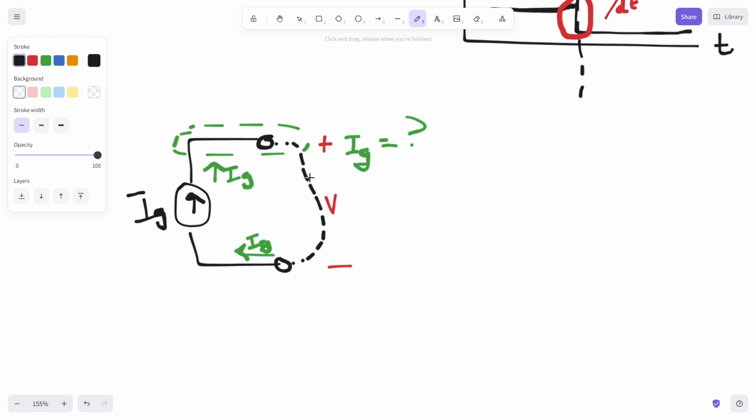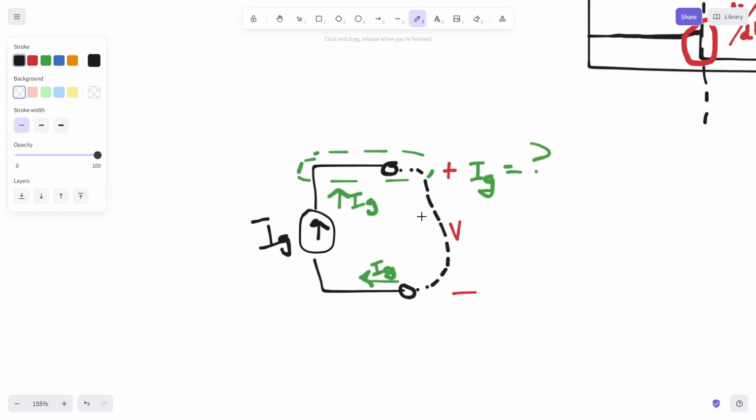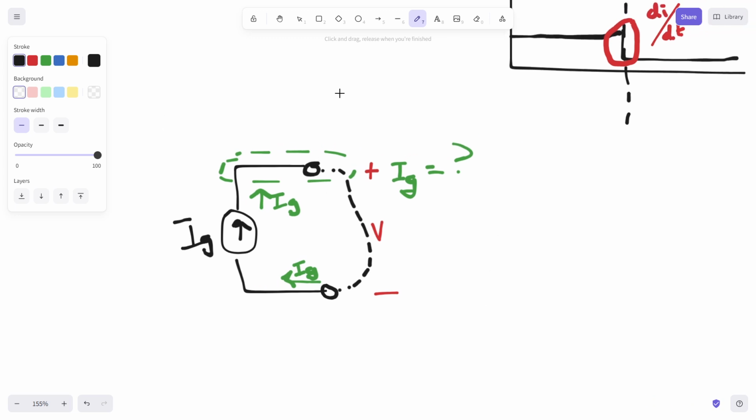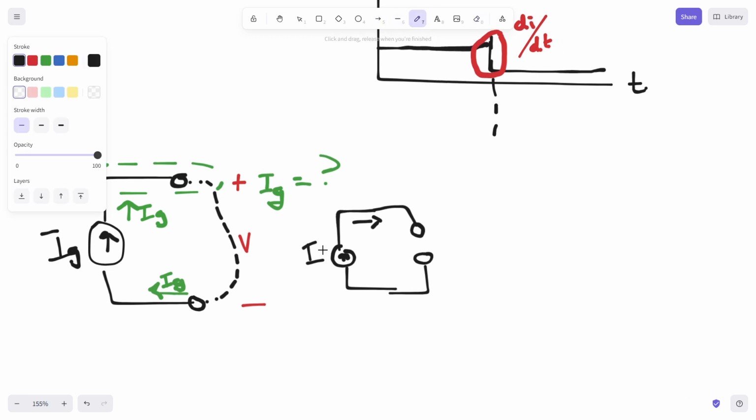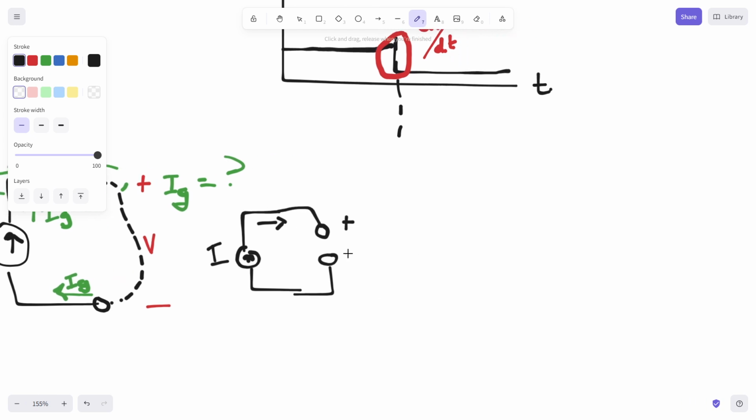One thing that I've run into in the past with LTspice, a circuit simulator that we'll probably get into one of these days, you set this into a particular node, but let's say that it's driving into a switch that's actually open. Well, let me just go ahead and finish drawing this little thing. So if we have this switch that's just open, there's nothing going on here. Well, LTspice is going to look at this current source and say, okay, we're trying to force a current through this node. And so what's going to be our voltage at this point?